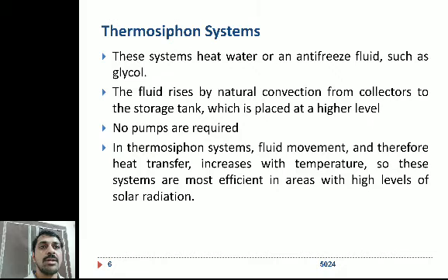So as the water gets heated in the collector, naturally it will rise up because of the density difference. The hot water is having a lower density compared to cold water, so automatically it gets risen up. That phenomenon is known as thermosiphon action. So fluid rises by natural convection from collectors to the storage tank. So obviously the storage tank is usually placed at the higher level than the collector. So there is no requirement of any pump. So naturally the hot water is risen up, the circulation is maintained naturally by the thermosiphoning action.